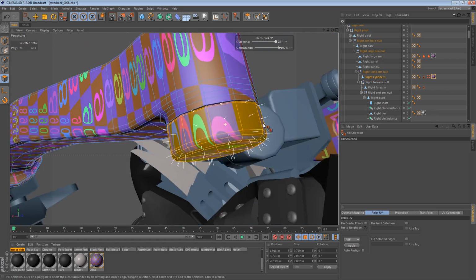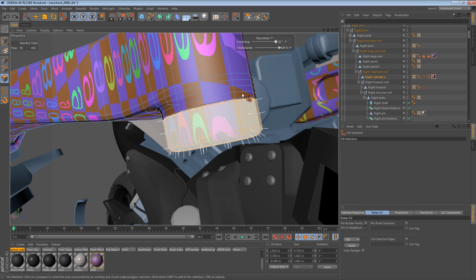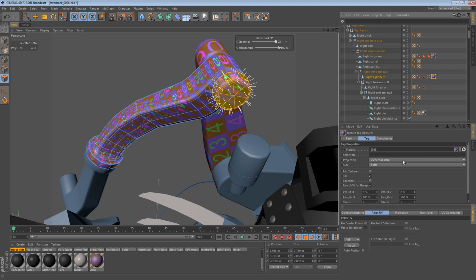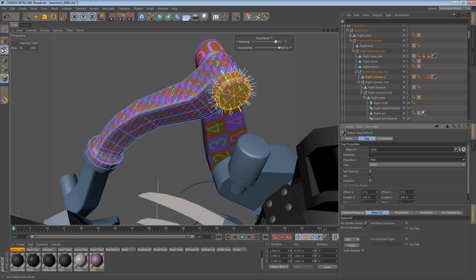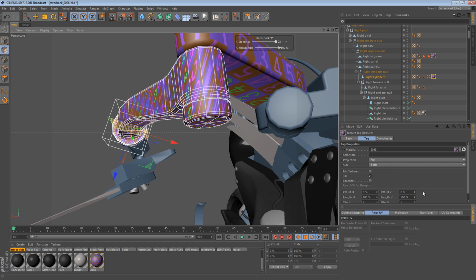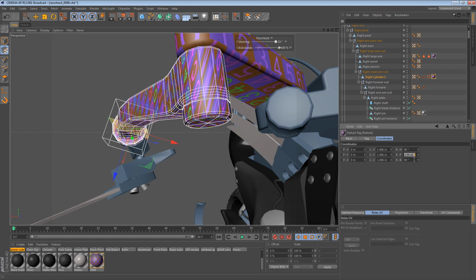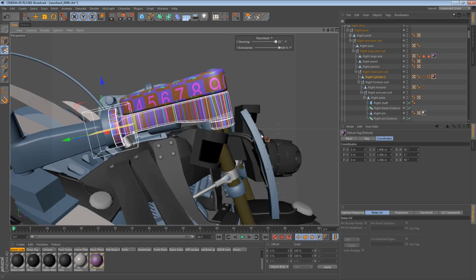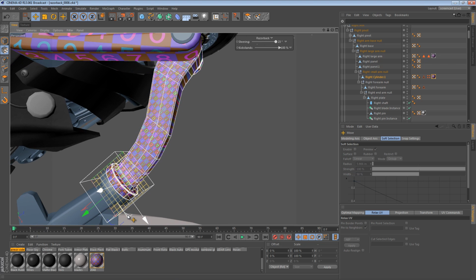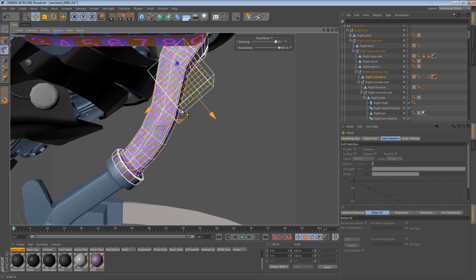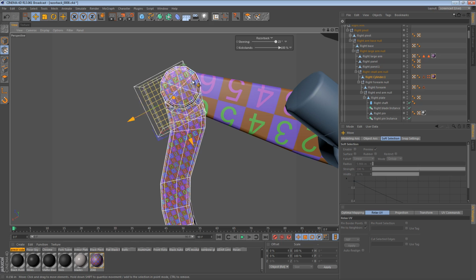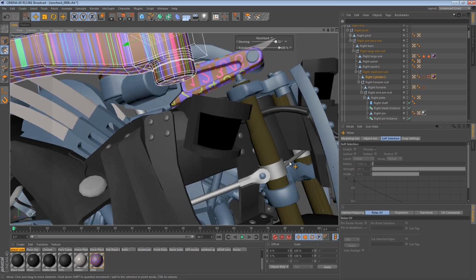Then, once I have that selected, I kind of want to tear it away in the UV space. But before I do that, I probably want to map it. So I'll do that as a flat map. Change it to flat, and then just make sure this is the correct orientation. So you can go to coordinates, and we can see that if we zero it out, it's pretty much in the right coordinate system already. But what we're really talking about is sort of imagining if it's there, and then that allows us to position it right there and start mapping.